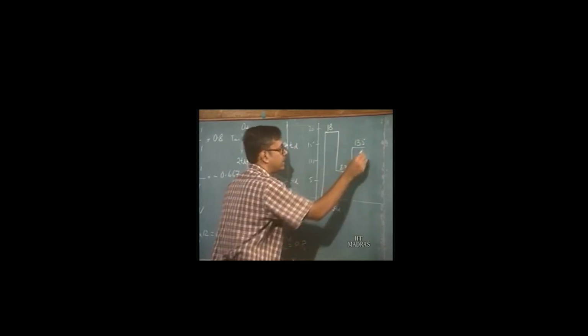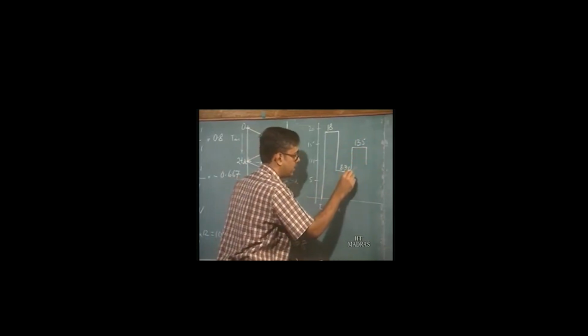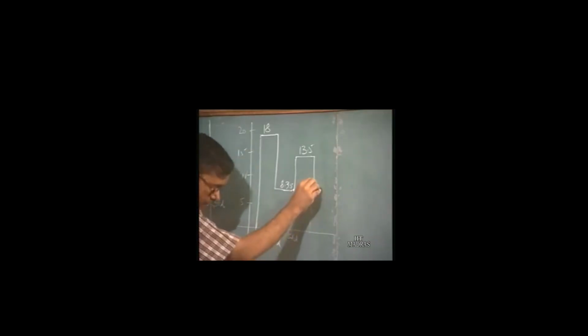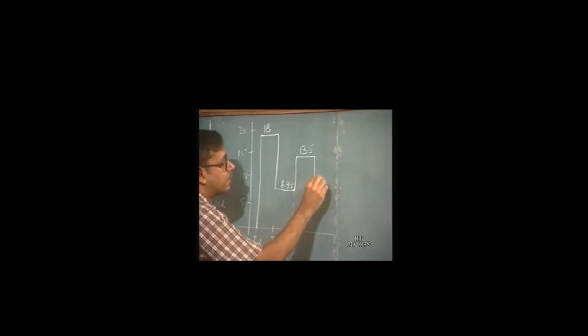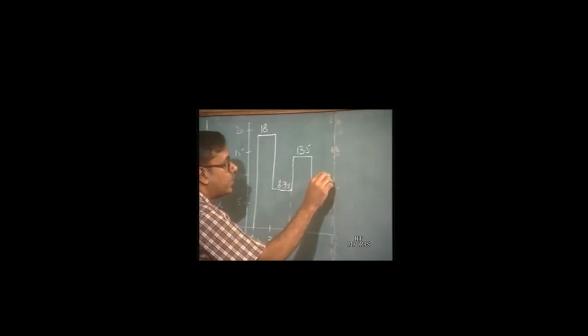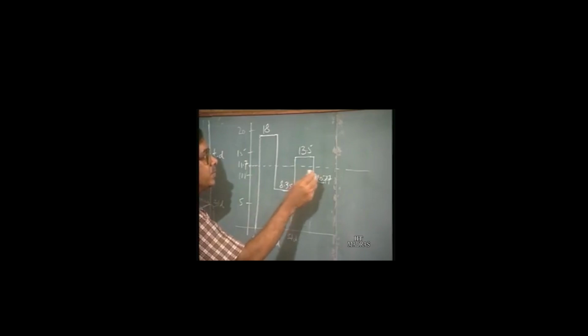Similarly, if we carry on this analysis, we find that at 5 Td, at 7 Td it goes down to 10.77. So finally, if we carry on this analysis for more lengths of time, you will find that it finally settles down to the value of 11.7 volts, which is the expected value.